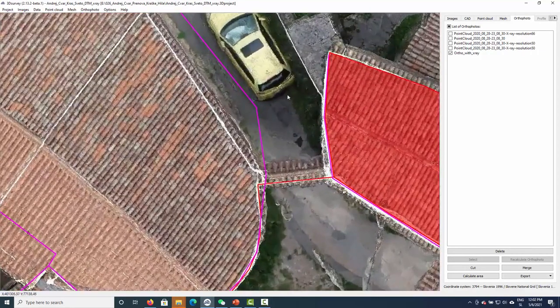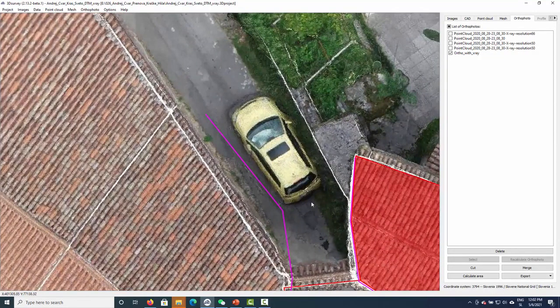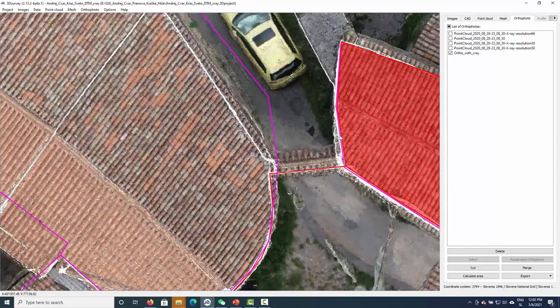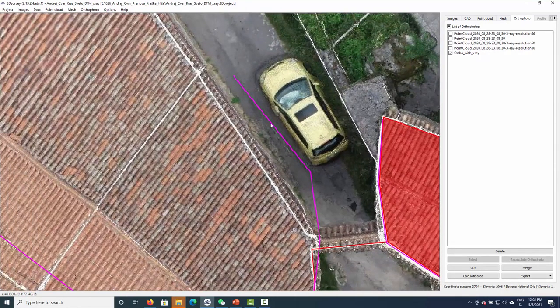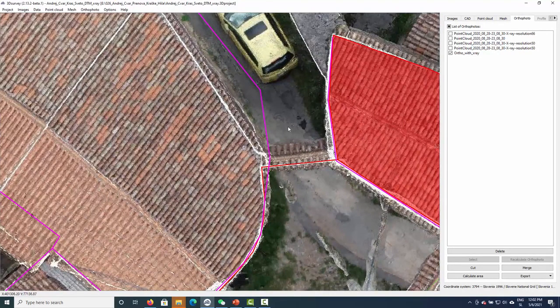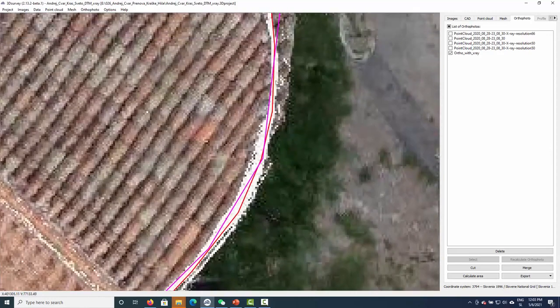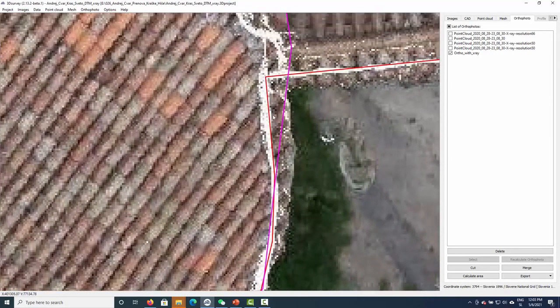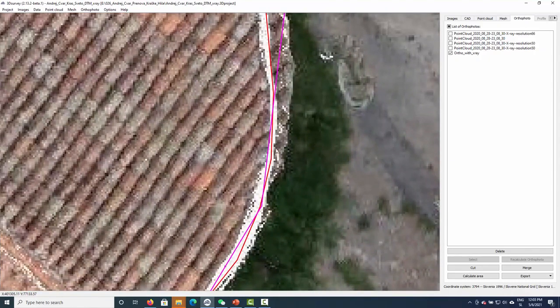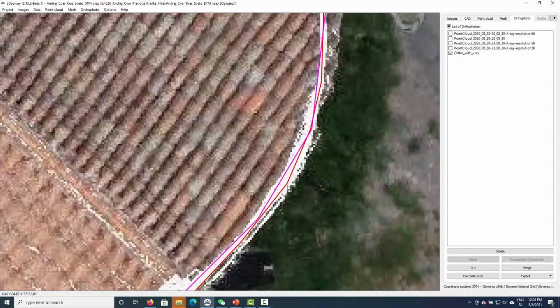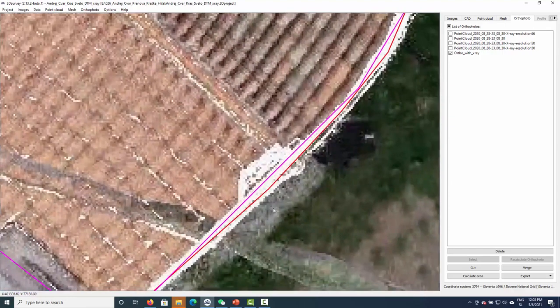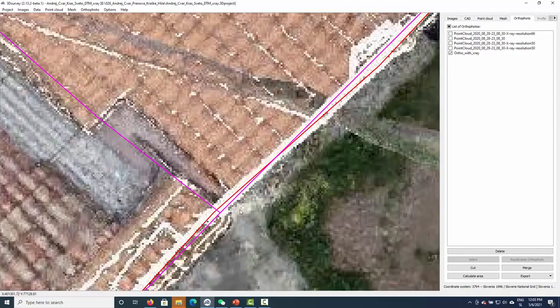Then his problem was that this courtyard back here he wasn't able to see, so probably what he did was he saw this corner, and when he was drawing the map he just took this line and added it here and said, okay, here goes the back side of the wall. So here was a small mistake that he made. If we check how we defined the walls, we see that with 3D survey we were able to take all the small details, we were able to define the walls more accurately because it was easier to put those points here. You don't have to move there with your signal and signalize the point.